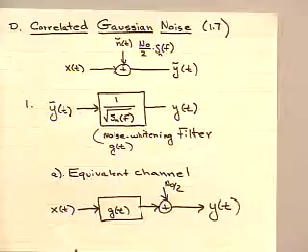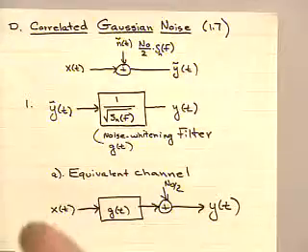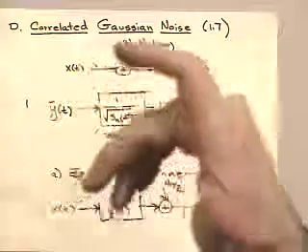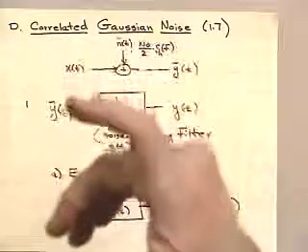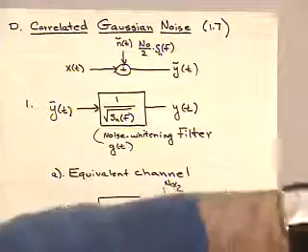And so I'm exactly back to the situation that we just modeled, which is intersymbol interference. Okay? The intersymbol interference is characterized by G of t. So you can kind of look at noise and pretend it's intersymbol interference as a channel. You actually get some intuition. Take the noise and invert the Fourier transform. And look at that. That's kind of like a channel. That's telling you equivalent effects.